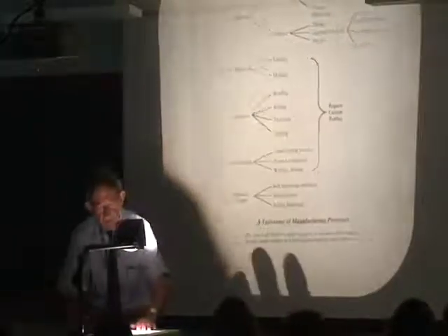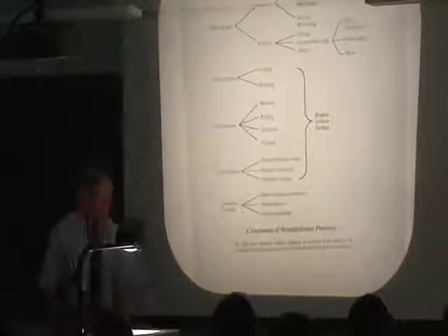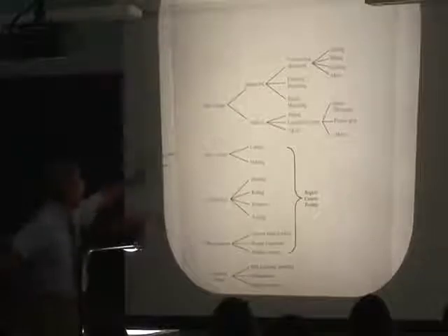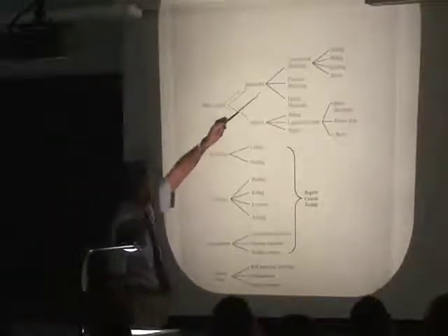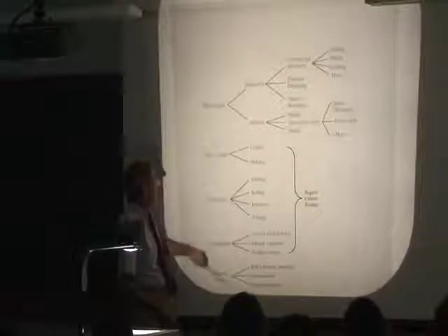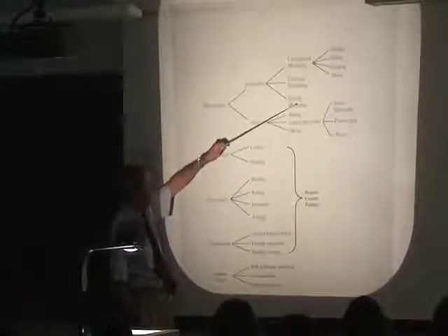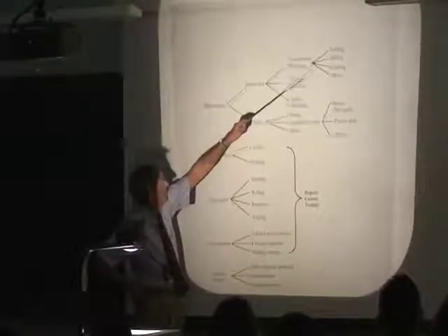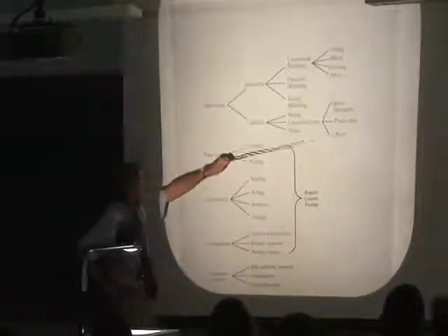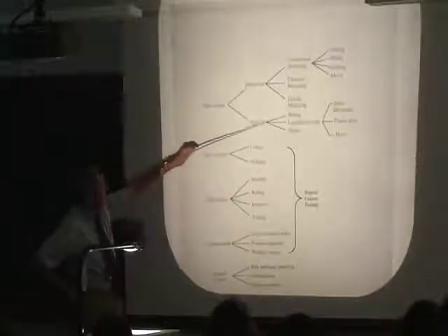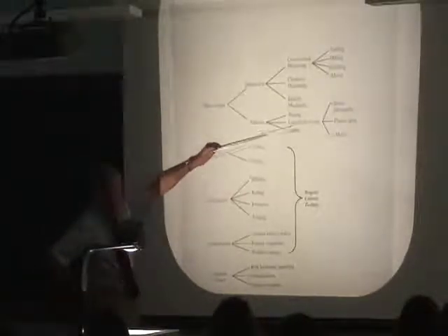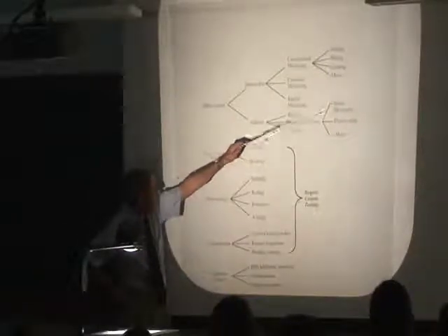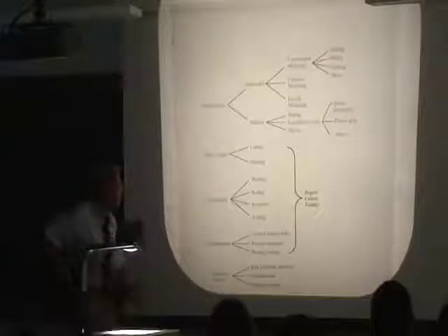Now, we can say more than that. If you look up here on the mass change processes, well, you have the subtractive processes. There's conventional machining, and there's chemical machining and electric machining. All of these remove material. In conventional, you have turning, milling, grinding, and so on. Under additive processes, you have plating, the layered freeform ones that are really coming into play now, like plasma sprays and stereolithography, and there are more of those.